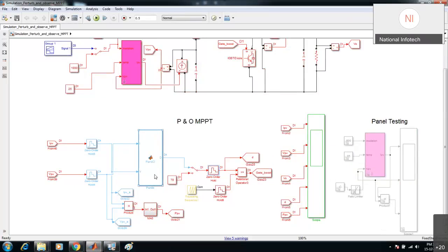We want this MPPT to give the duty cycle changing reference at a lower rate. You see, the sun's irradiation change does not occur abruptly. It is gradually changing, as the clouds come and the shading happens. That's why we normally keep this MPPT slow.